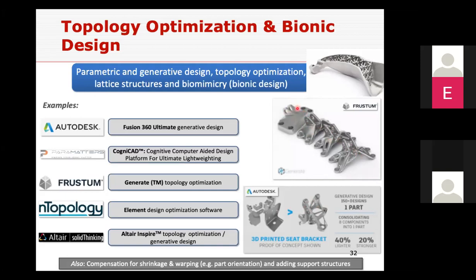Means I have, say, some aerospace application like a bracket, and I need to make it more lightweight. Why? Because of a more fuel efficient system. Wherever possible, I want to minimize the payload, so I want to introduce the lightweighting structure concept. Then you can go with the topology optimized structures, where you can make use of several tools that are available to do this topology optimization. But finally, I would like to fabricate it, so you do design for additive manufacturing.